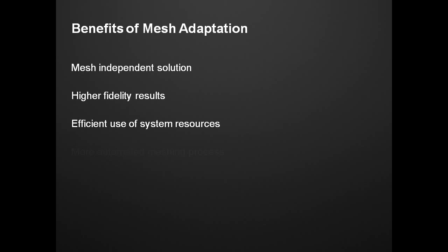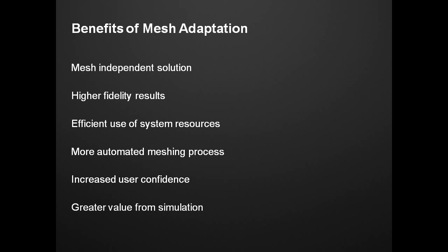While mesh refinement regions are still available for advanced users or users who want the ultimate level of control over the simulation model, the meshing process can be simplified down to two steps: auto-sizing and enabling adaptation. The validity of a CFD solution is based in large part upon the quality of the mesh. Users can rest assured that their solution is of greater quality with less setup input. These benefits combine to enable users to get more value out of Simulation CFD 2013.